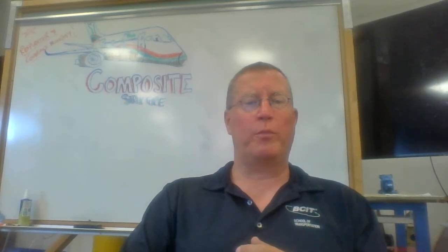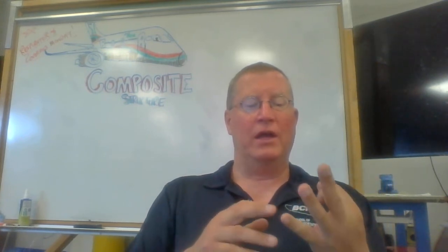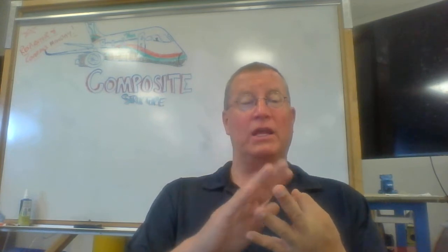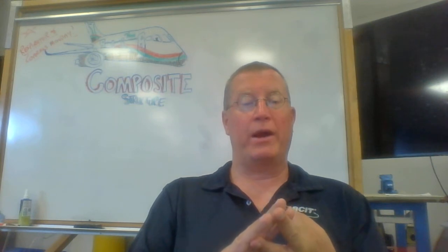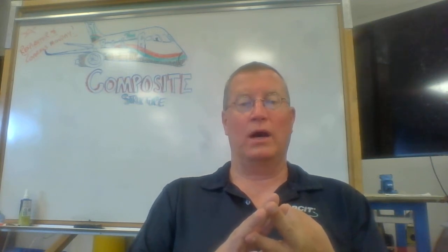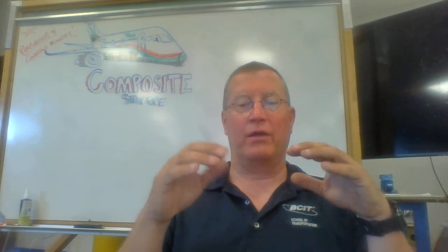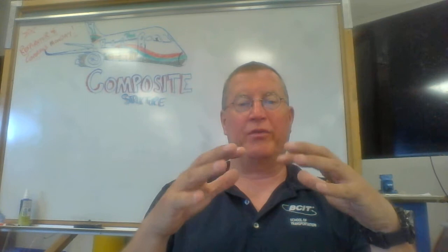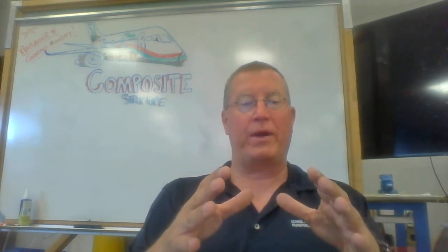One of the tools that we'll probably use during that process would be a hot bonder. The hot bonder is going to provide us with a couple of things. It's going to provide us with vacuum, it's going to provide us with controlled heat, and it's going to give us some sort of feedback as to exactly what's going on during the repair, right? We'll have thermocouples in there on top of our heating blanket, providing the control box with feedback as to the temperature over the repair.